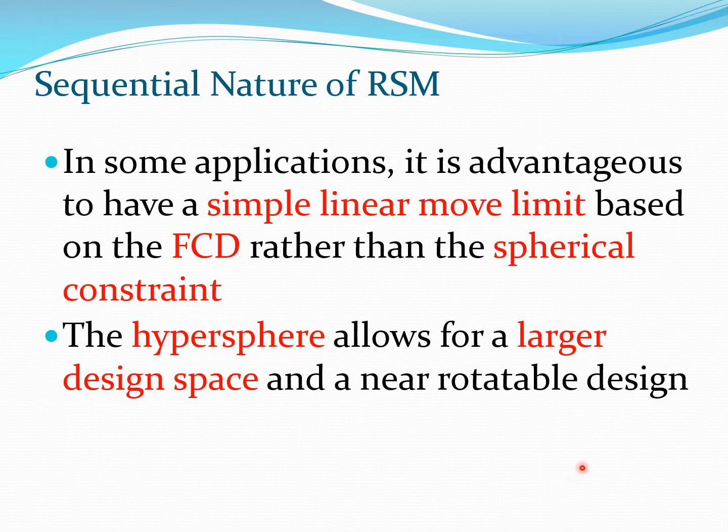Now whenever you are dealing with simple linear move limits, then of course we have seen that the face-centered design is a better choice than the spherical constraint. However, using spherical type of constraints such as the CCD based design lets you have a larger design space. It also gives you a near rotatable design, and that has some theoretical good points going for it.